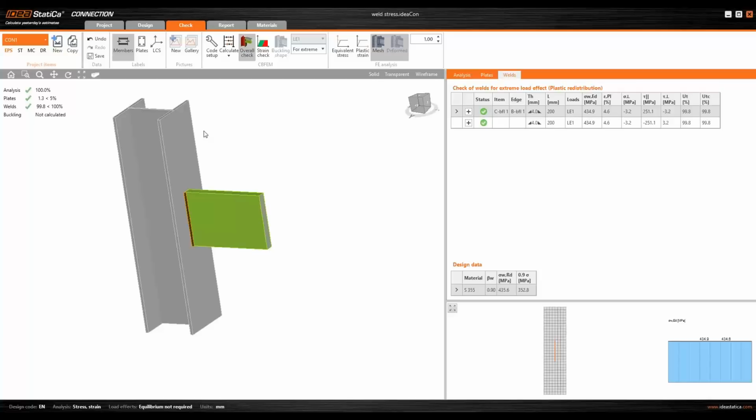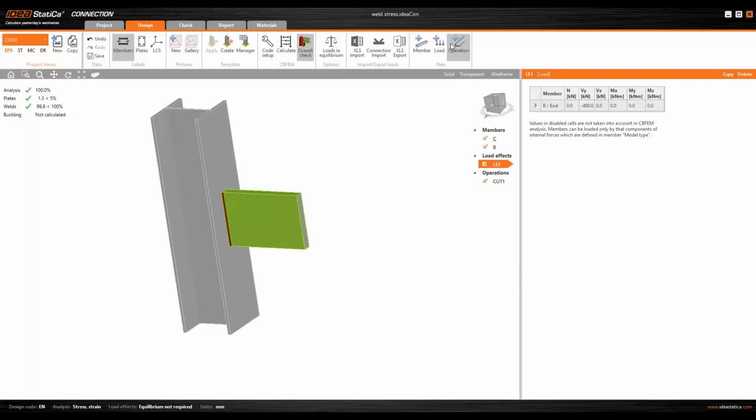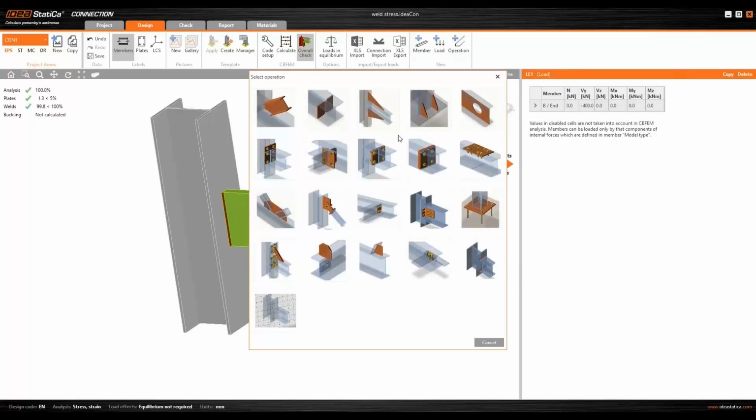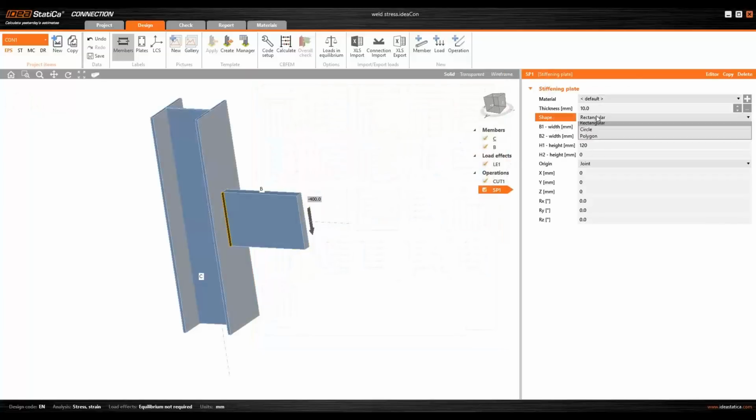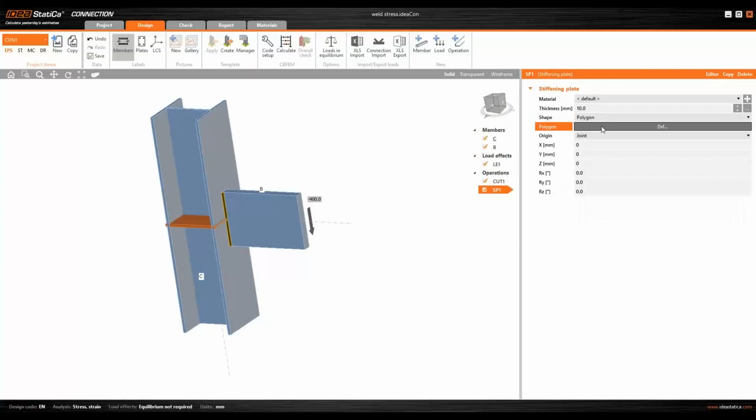So if you have it in AutoCAD, for example, as an object, you have to explode it out to just simple lines, and then you're able to import it. Another error comes when you don't close the DXF file before you import it, because when it's opened, you cannot read it with IDEA. So yeah. And maybe I also know that you have to check the units.